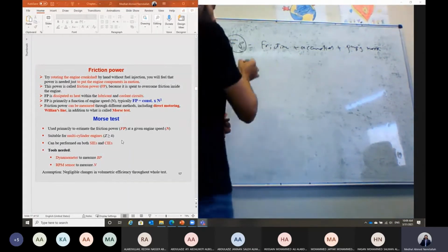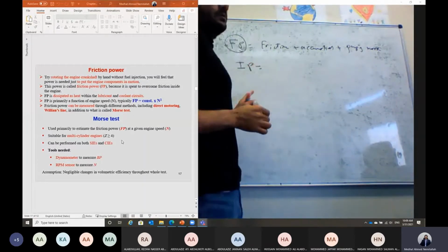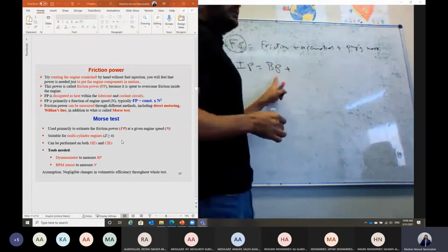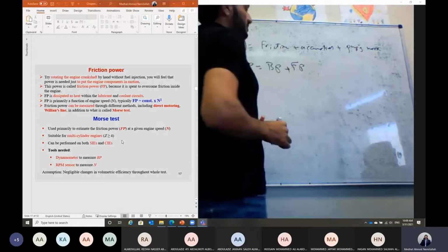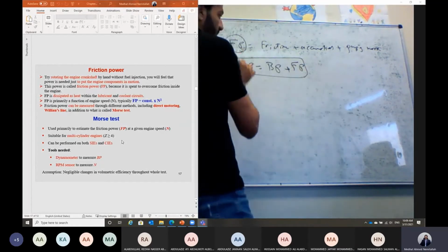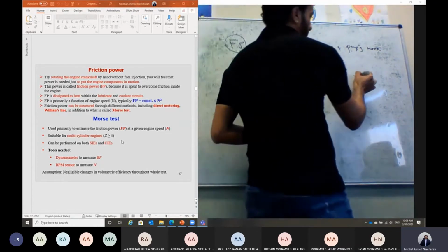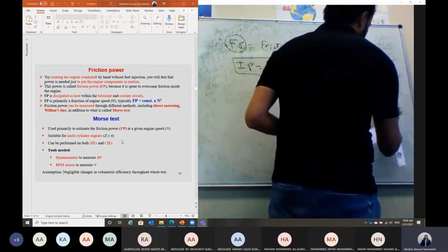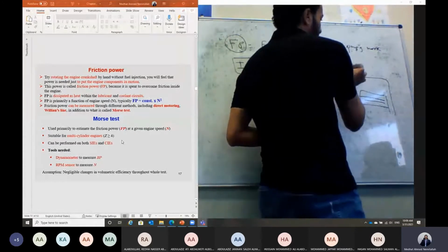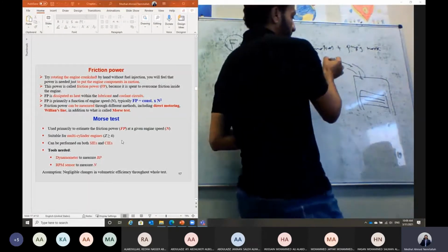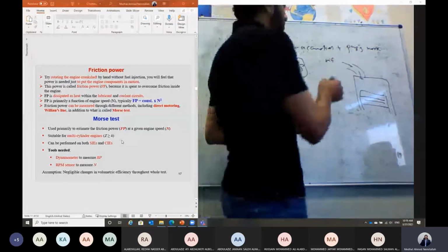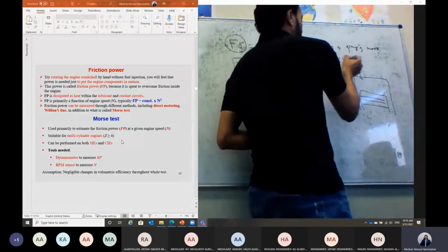And we see the difference between the indicated power, which is the power generated inside the piston, and the brake power should equal the friction loss power in this case. So the indicated power is equal to the final brake power plus the friction loss power. If you look at the sequence, Shabab, of the energy conversion for any internal combustion engine, through the intake valve here, we have the charge coming. So it has the chemical energy of the fuel, which is equal to m dot fuel multiplied by the lower heating value of this fuel.